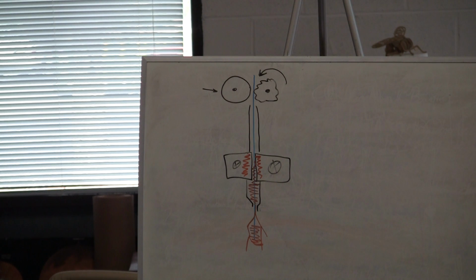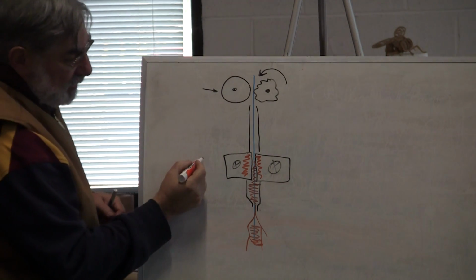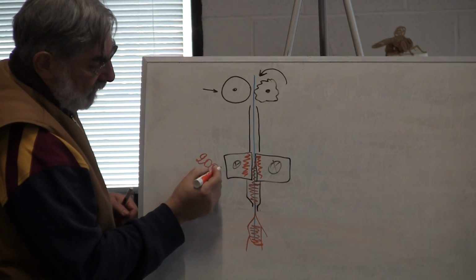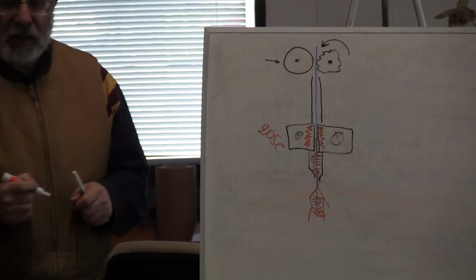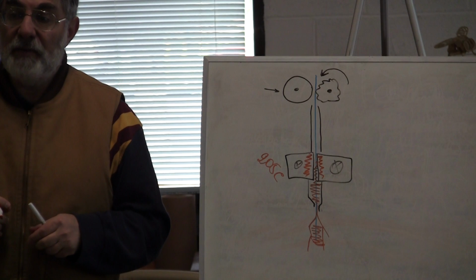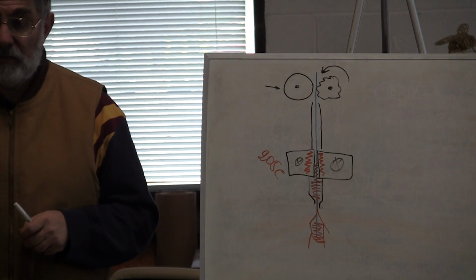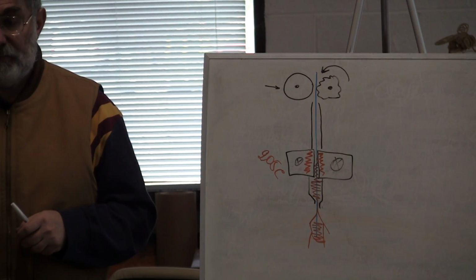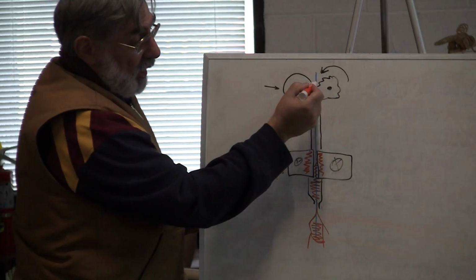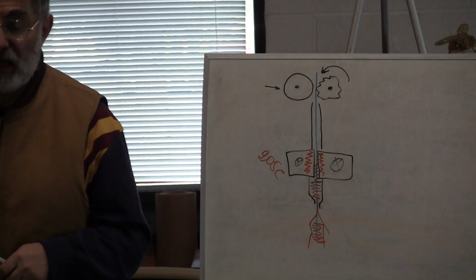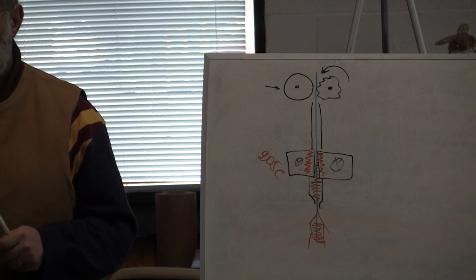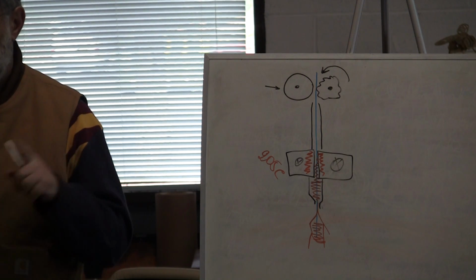Here's the tricky part. This is running at, let's say, 205C. The last transition where filament becomes soft is 65C. If you allow this part here to be 65C, nothing useful will happen because the filament will just get mushed.